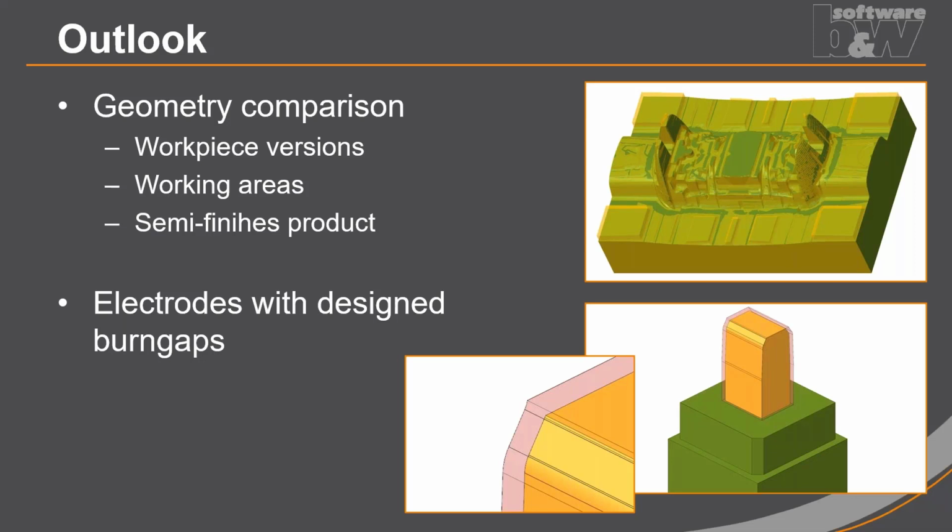and also adding semi-finished work pieces to your assembly so that you can take a partly finished model from Creo NC or any CAM software and load it to your electrode assembly to see where you still have to manufacture with electrodes. But the last point is a little bit more complicated because those models are normally only tessellated data, and it will be complicated to do the comparison on tessellated data in that case.